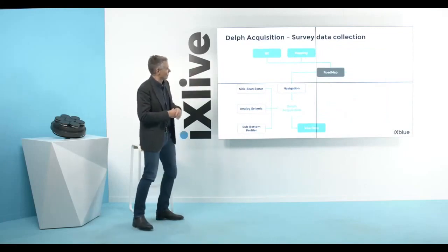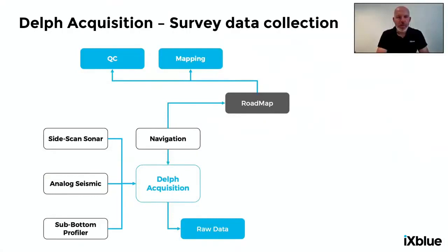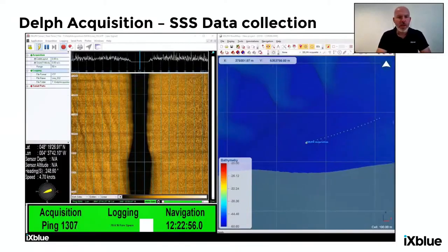And here's just the focus of the acquisition. Yeah, the drawing is very simple. We come from the sensors and the navigation data to the raw records. It's very essential in there to log only raw data, do not do any pre-processing. Data collection from the navigation, proper timestamping, and using the standard industry formats, XTF, SEG-Y, and so on.